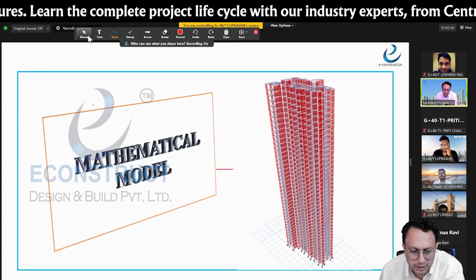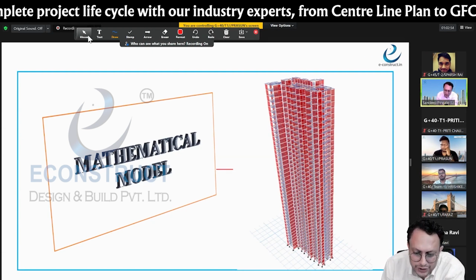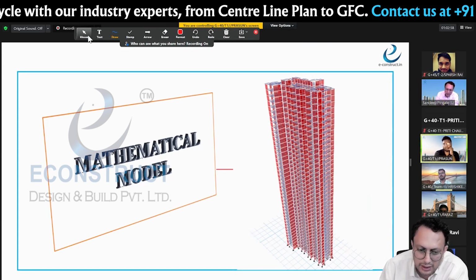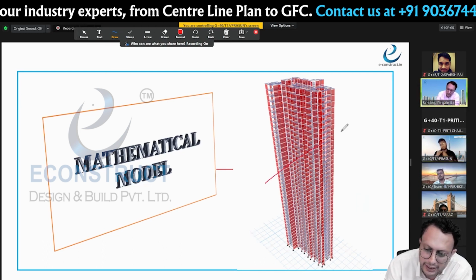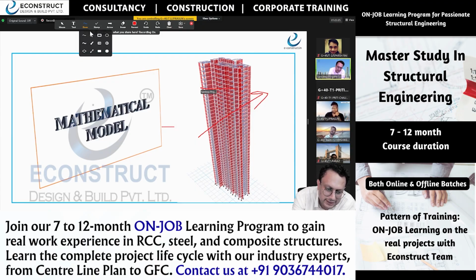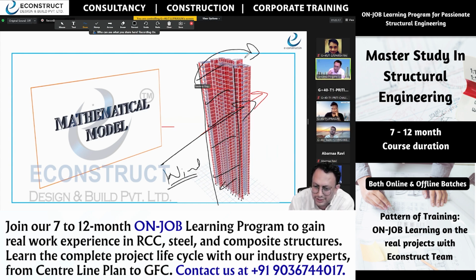Yeah. Can you show me the mathematical model? This is the same mathematical model in which you are getting almost 4 meter deflection. Yes, see what is happening. You are getting wind deflection because of the higher surface over here. Please understand why you are getting it. You have a higher surface and height here, and when the wind is blown in this direction on the structure, you get the deflection in this direction.